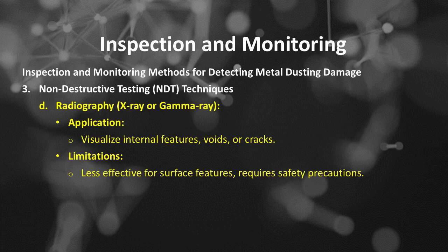Number D of NDT techniques is radiography, X-ray or gamma ray. Application of radiography techniques is to visualize internal features, voids, or cracks. Limitations of radiography techniques are that it is less effective for surface features and requires safety precautions.